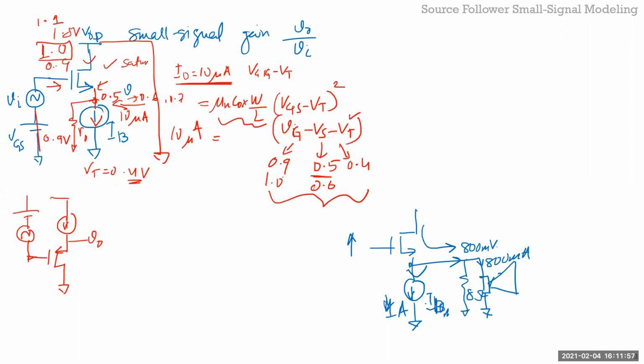And that's why all the big power amplifiers will have huge current. In IC, you don't bias it this high a current, but outside you'll bias it at this higher current, right? So when the signal is swinging, this is always 1 amp, right? So let's say you need 800 milliamp here. What should be the source current here? 1.8 amps, right? When this is 500, this will source 1.5. And when it has to go to reverse, so let's say the current needs to flow 500 milliamps in this side, this way, then this only needs to supply 500 because 500 plus 500 is 1 amp.